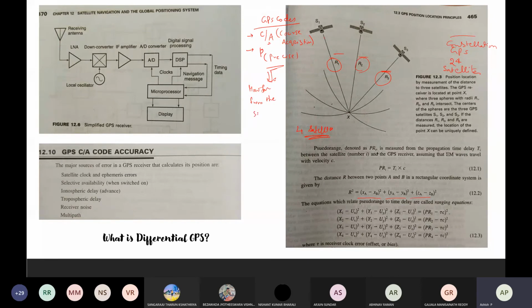Okay, so how this information is organized: all these satellites use spread spectrum, so CDMA. When the receiver wants to latch to a particular satellite, it will use the pseudo-random PN sequence of that satellite for reception. Since it is CDMA, all the satellites send their information at the same time and same frequency. Once the GPS receiver is on, it will search for the different satellites.